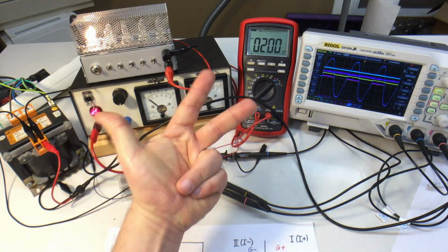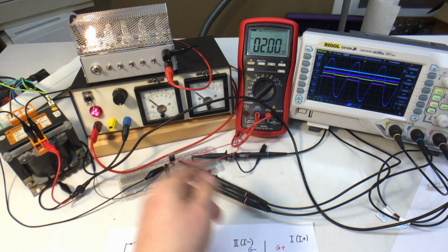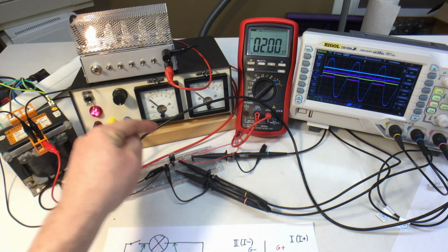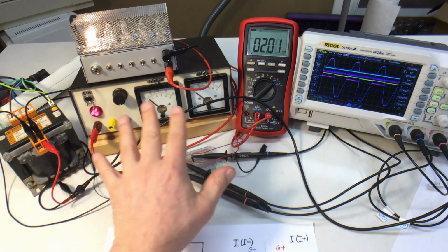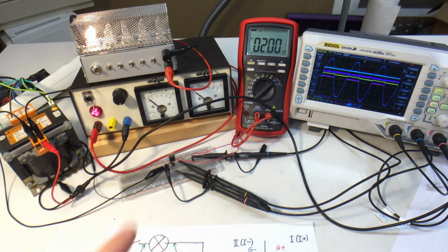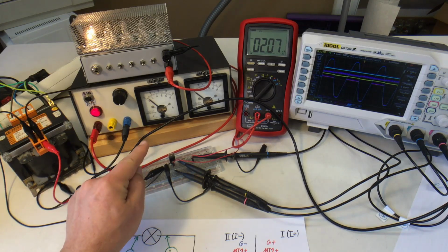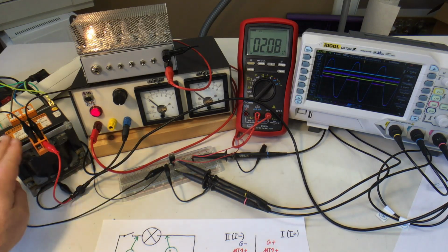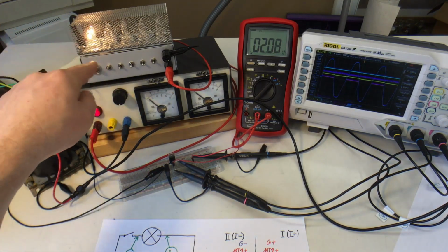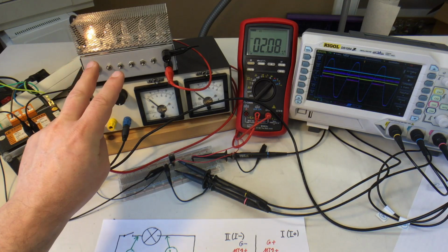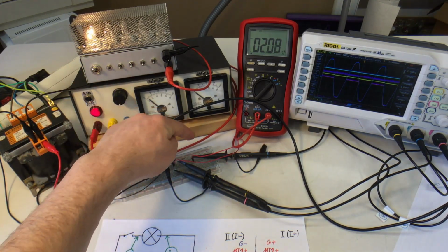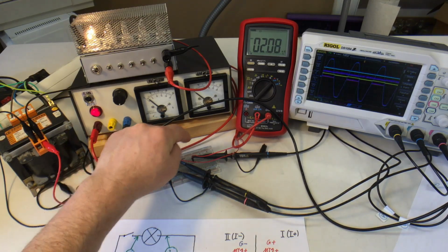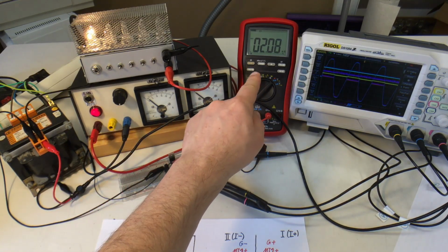Welcome back to the third and last part in this mini-series about TRIACs. And as promised, this video will be about practical considerations. This time my TRIAC is actually switching AC 24 volts RMS from this transformer through my electronic load. And the gate is driven by my power supply and a little series resistor and gets currently 2 milliamps.